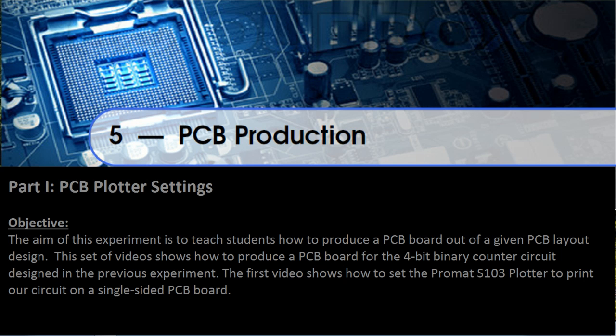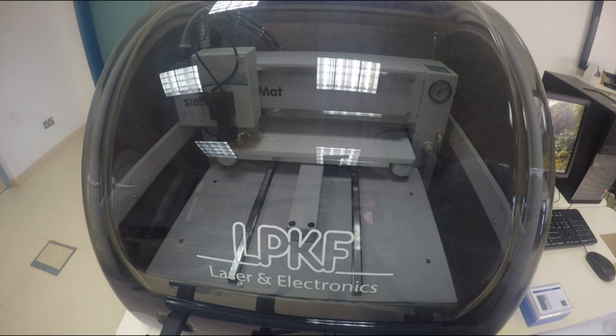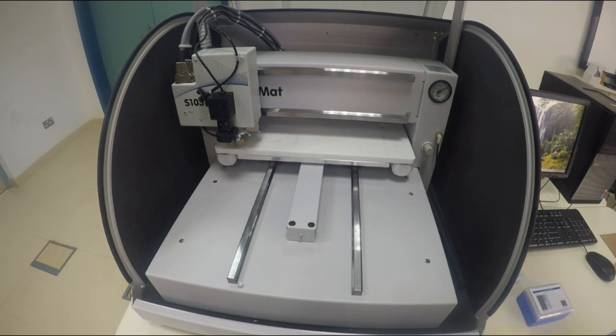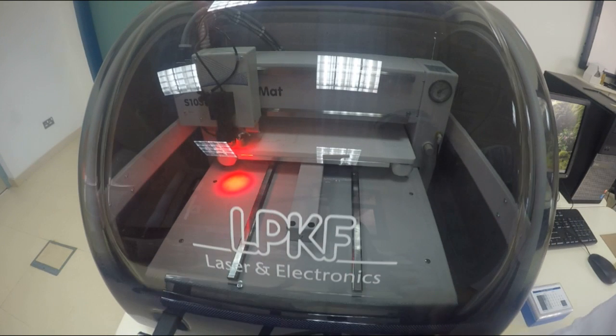This set of videos shows how to produce a PCB board for the 4-bit binary counter circuit designed in the previous experiment. The first video shows how to set the Promat S103 Plotter to print our circuit on a single-sided PCB board. To start the PCB plotter, open the cover and turn on the power switch located at the right side. Make sure to close the machine cover before running the plotter software.